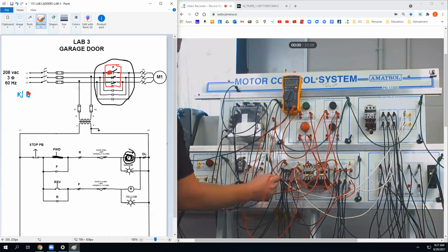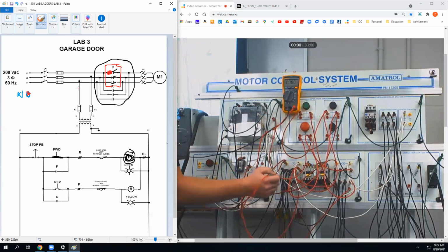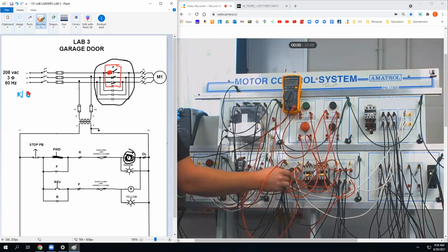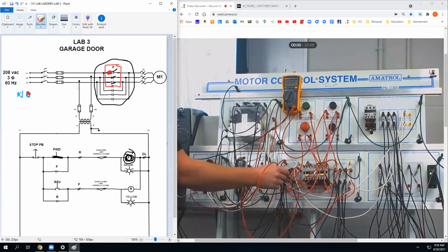Well, let's say I got 120, 120, and like 19 here. Is 19 a usable voltage? No, you're catching some kind of stray transient voltage or some induction from something that's giving you a reading. But this is no dice. So what do you think the problem is there?